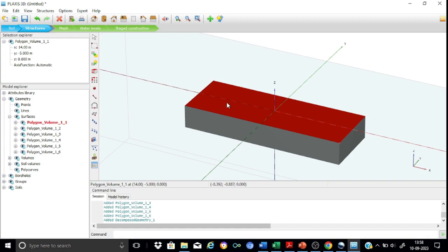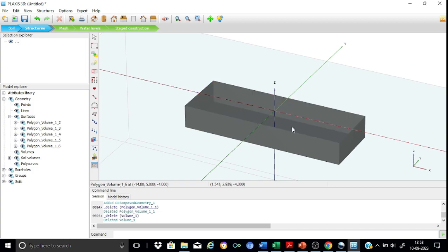Here we have got a top surface that is again created. Just delete it, and then as you can see, on the top we have got a volume. Just delete it. So now you will find that we got the required basement floor that consists essentially of 4 walls as well as a basement floor. So this is good enough for us. Now remember, right now the 5 surfaces are surface entities. So now let us convert all of them into plates. Select the multiple surfaces.